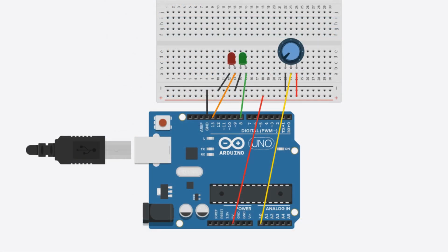This thresholds layout shows similar wiring to the previous threshold layout, except for the additional LED, and the switch representing the piezo has been replaced with a potentiometer. The potentiometer is perfect for the prototype because it provides precise inputs to test the various thresholds. As with the other examples, the LEDs and potentiometer can be replaced with other sensors and actuators with minimal or no changes to the code, in most cases.